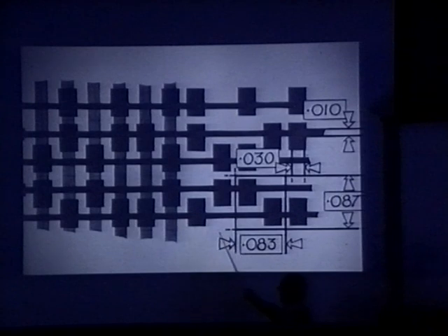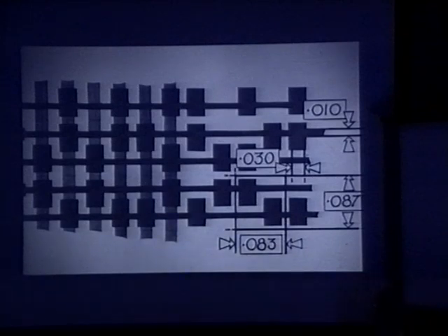The key thing that an engineer needs to know, I'm sure you all do, is that square inches over inches is equal to picofarads, provided the dielectric constant is 4, and as we all know, dielectric constants always are 4. So square inches over inches separation for a parallel capacitor gives you picofarads.